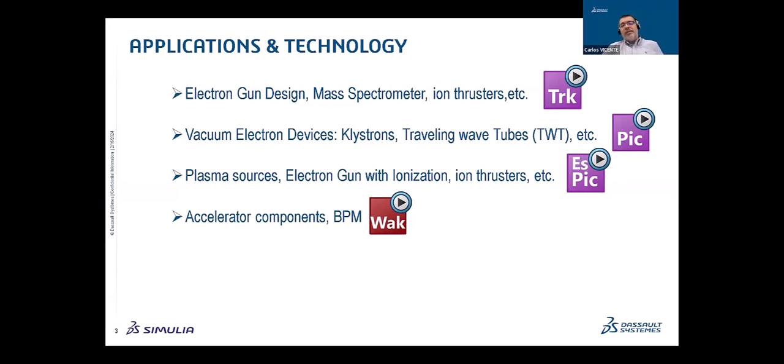The different integration techniques allow computing the wake fields depending on the geometry of the passive RF components. This solver also supports relativistic effects and low beta beams for applications like the ones mentioned there, for accelerator components or beam position monitors.